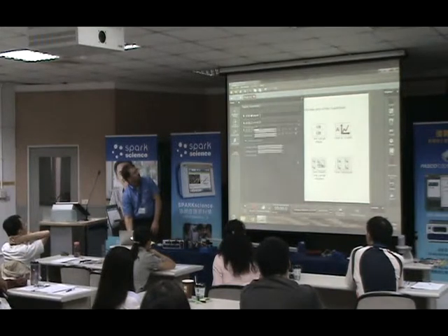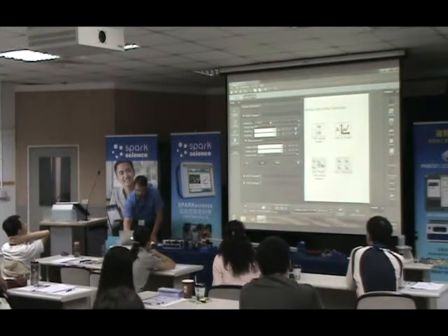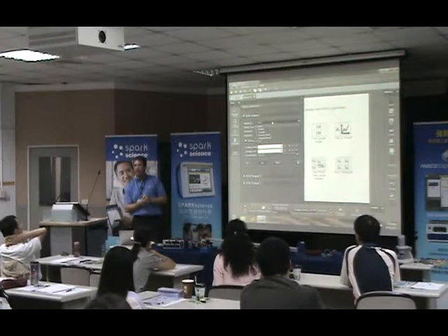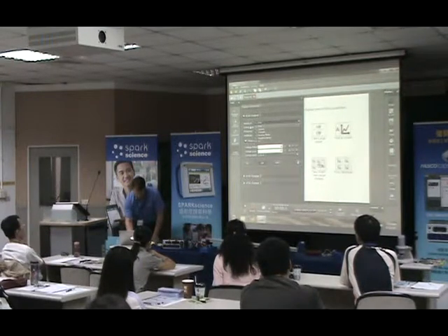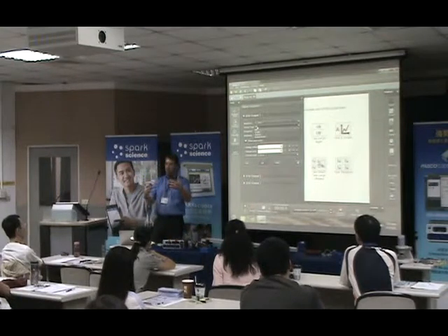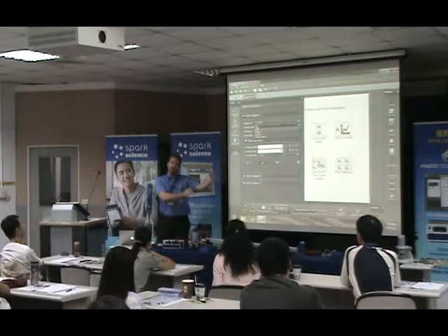And now we're going to switch over to our signal generator. Okay? So, like I said, the signal generator has a couple of nice features. One is the wide variety of signals that it can output. The other nice feature is it has a sweep ability. So I'm going to single sweep a range of frequencies in this activity. I'm going to go from 1,000 hertz to 70,000 hertz.